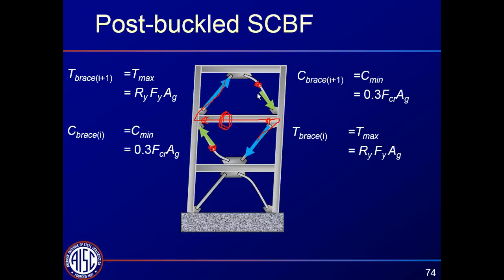That's a good question. Case 2, in the example that I showed with the collector force, it really only gave us the maximum force outside of the frame. It didn't give us the maximum force inside of the frame. So I would say generally, if you analyze case 1 and case 3, you probably have what's going on inside of the frame covered, and you don't need to worry about case 2. Outside of the frame, though, you do need to worry about case 2.